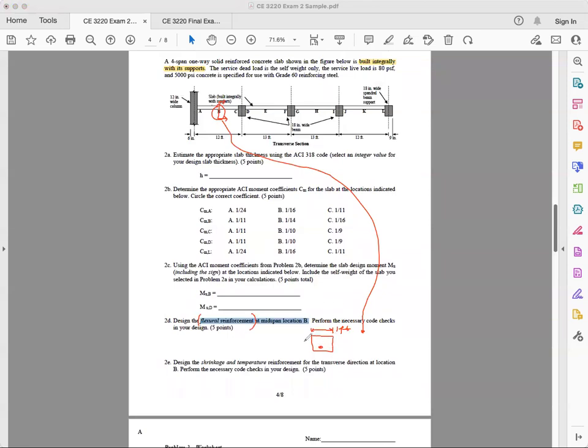And the applied moment here, Mu, as I show from here, is 4.928, okay? 4.928 kip foot per foot. So that is your design moment. And then you pull out your lecture notes on the one-way slab design and go through the process, and then you should be able to design for it. Okay, design for it. So that's 2D.